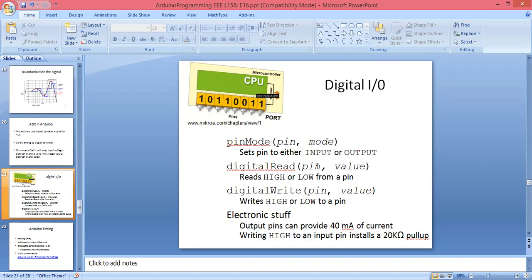here if you are writing digitalWrite in brackets, this is the digital one, so we can take the digital pin. Where do our digital pins run from and to? D0 to D13. So we will write digitalWrite in brackets D13 comma HIGH. So what does that mean? At the pin number 13, the LED will glow because you are giving the higher value. Higher value means you are giving 5 volt supply.